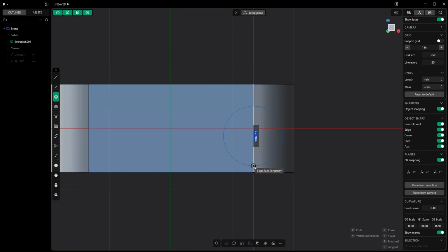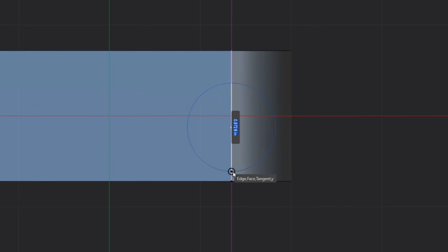All right, so the actual diameter of this is going to be 7/8, but that is the inside diameter for the 1/2" PVC to fit into. And so what we actually need to do is add the wall thickness. Again, based on specs, the wall thickness changes based on the size and the schedule.